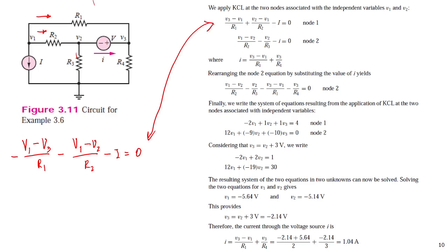Are these two equations the same? Right? It's the same equation, right? Okay, so we can consider any direction, but do not do the wrong calculation. Keep the direction and the sign corresponding according to the sign. So you don't need to worry whether the current flows in or flows out. Which one we use as the higher voltage is up to you.